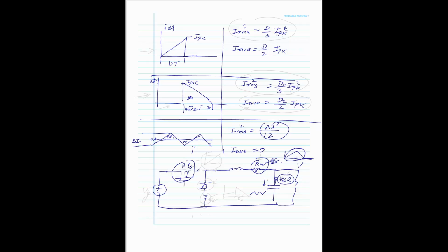Now, what would be the power dissipation here? That waveform, remember, would start at 0 for discontinuous, come up, and drop. Well, this waveform is right here. So we use this RMS current times the RDS on there to find out the dissipation here. What do we use here?